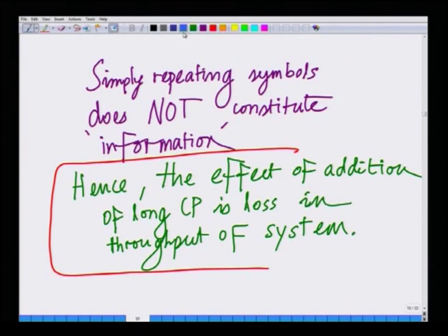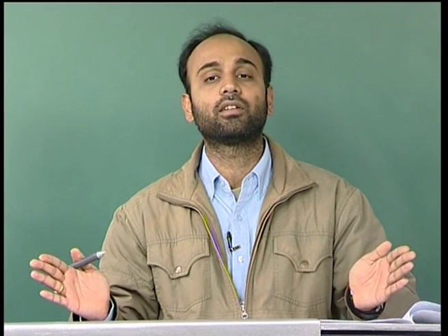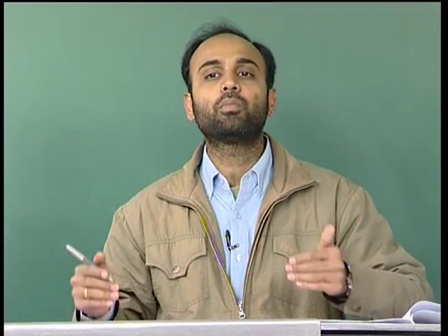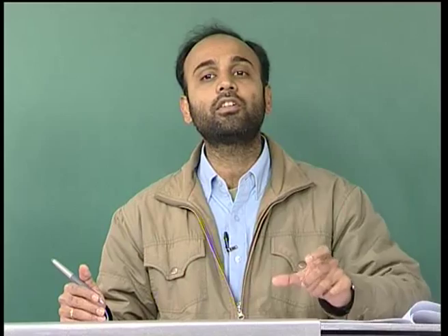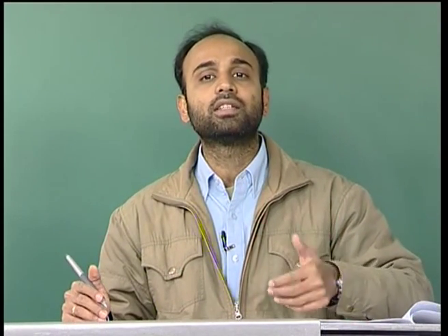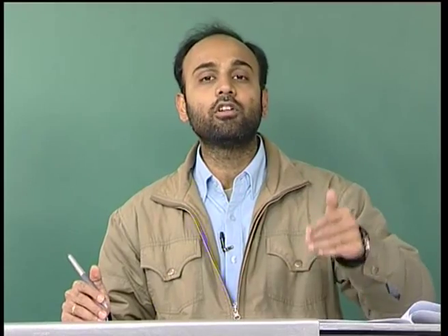What is the catch? The catch is essentially we would like to have a longer cyclic prefix, much greater than the delay spread of the channel, so that you can protect against intersymbol interference. However, the moment you start using longer and longer cyclic prefix, the cyclic prefix becomes dominant, and then you will start losing in terms of effective throughput of the system. So, there is a trade-off in terms of cyclic prefix versus the throughput of the system. One has to manage the length of the cyclic prefix such that the throughput does not get affected significantly.